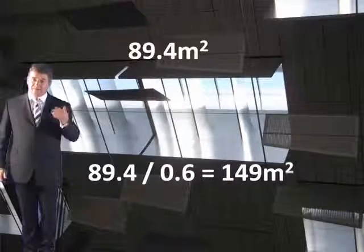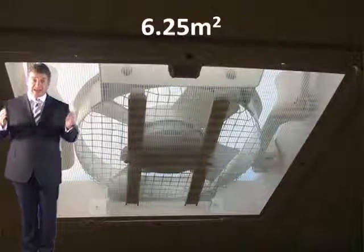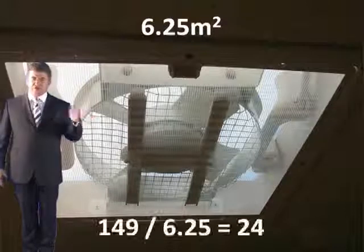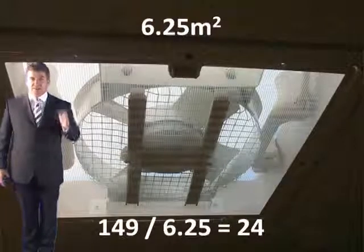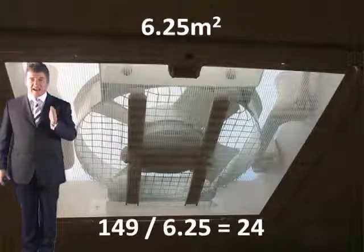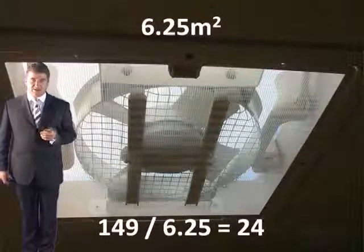Now don't forget that ventilators don't come bigger than 6.25 metres, and that's because they can't test them any bigger than that. So they don't come bigger than 6.25. So you divide 149 by 6.25, you get approximately, we're going to need at least 24 ventilators. 24 ventilators, that is the absolute minimum that we need in each reservoir. So where do we locate these ventilators then? Where should we put them?